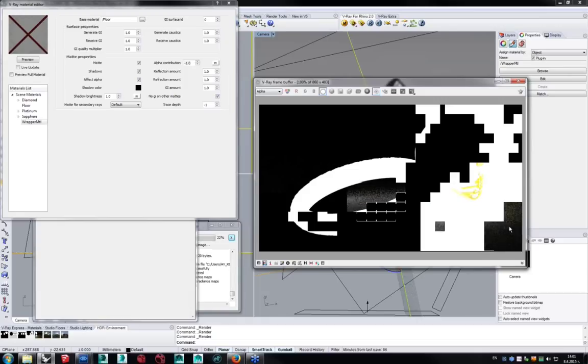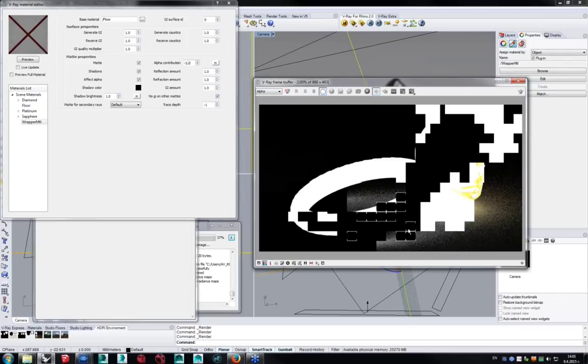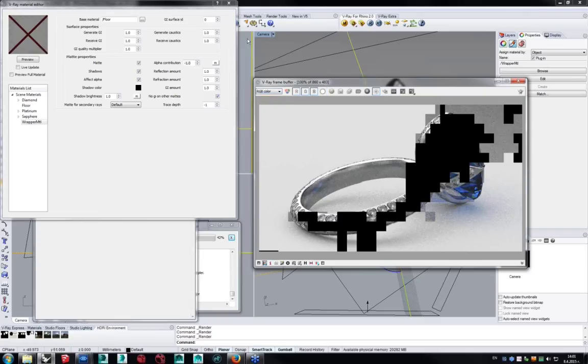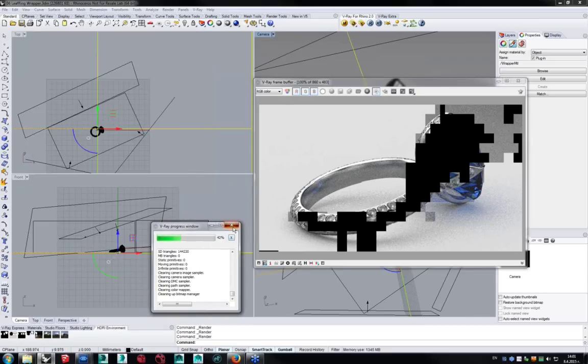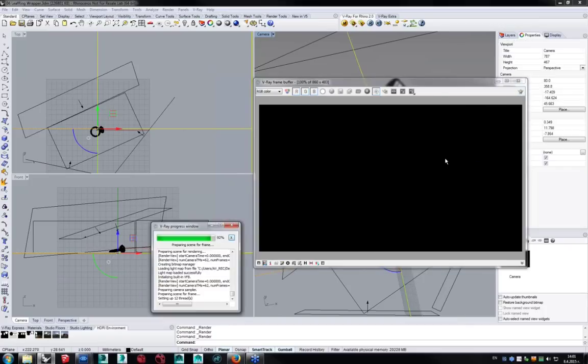So this is a really cool way of changing the background after you have rendered. It's just a very simple, very fast and straightforward setup that you can use to do that. Now once you're happy with these settings and these setups, you know that you'll be going to some compositing, although basic, you can go and enable all the VFB channels that you want. You can enable GI, diffuse, the lighting, you can use the reflection, the refraction, of course, the shadow if you want, the specular, and you can use Z-depth for simulating depth of field if you're not rendering with depth of field from within V-Ray, and hit render.